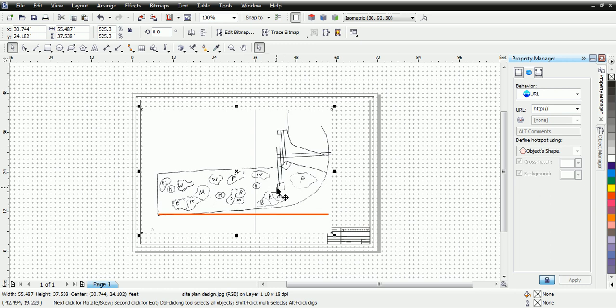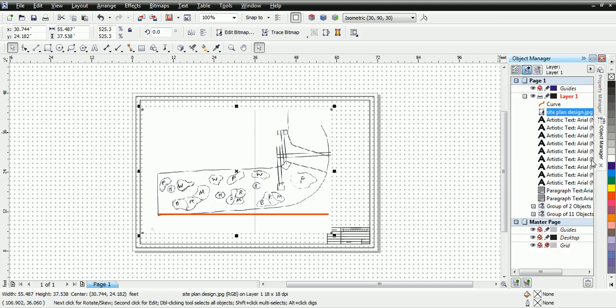on our Corel Designer page, it is our recommendation for you to add a new layer. You'll see over on the right-hand side of your Docker window, a new layer is added. You can rename this layer if you choose, but the benefit of adding a new layer is we can eventually turn off the imported site plan. Just as you would add layers or add pieces of tracing paper to your traditional drawing methods, using a layering system in Corel Designer will replicate the same process.